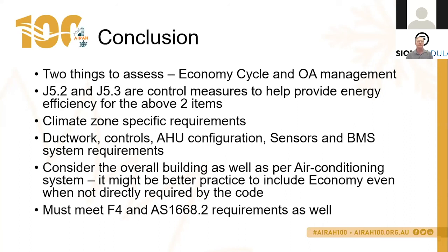The determination of the heat exchanger or sizing based on the outdoor air rates is based on making sure that it is energy efficient and therefore provides an energy saving annually. And it does take into account pressure drop, supply and exhaust fan, energy consumption, etc.